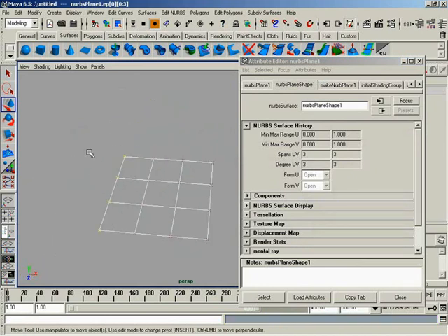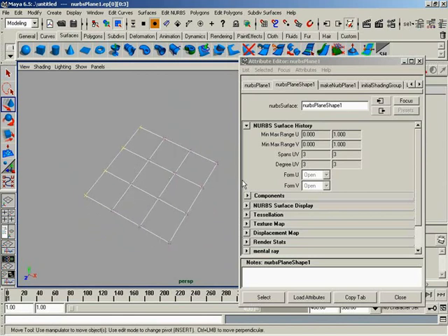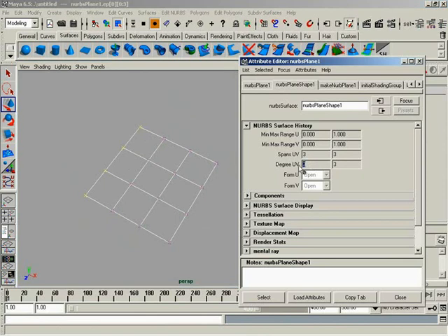Now, just remember, you can't move these knots around, or edit points. Remember, I can use those words interchangeably, and I will. Okay, you can also see, this is a very interesting thing to point out real quick, is the degree. We have 2 different degrees going on here. We have a 3-degree cubic going in the U direction and a 3-degree cubic going in the V direction. Yes, you can have a situation where it's a 3 and 1 or something like that.